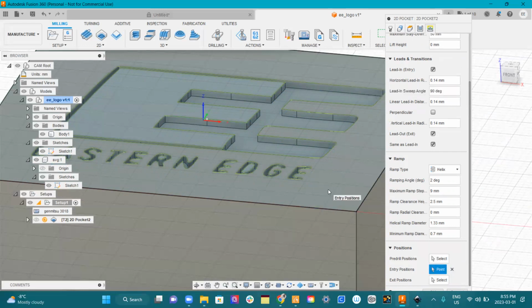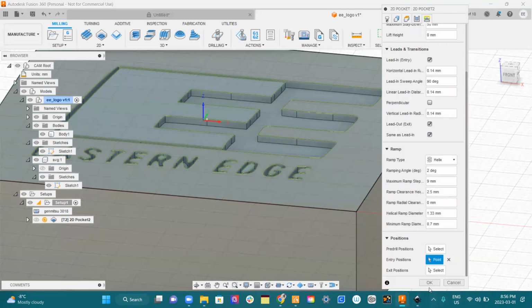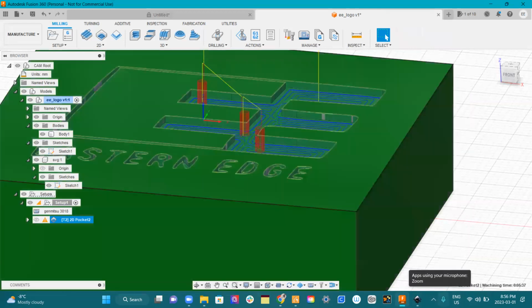Pre-drill: sometimes you want really crisp corners. If I'm doing a square, I don't want it to treat the square as a weird circle and start doing spirals. I might want it to pre-drill the 4 corners so that they're nice and sharp, and then cut down in between the material. If I'm really fancy, you can get the machine to cut with different tools. It'll use a drill to do the drill, then a mill to go sideways, and then a facing bit to do the flat part and the finishing. It's a whole thing. There's a lot to know. Machinists do a lot of training to get into professional versions of this.